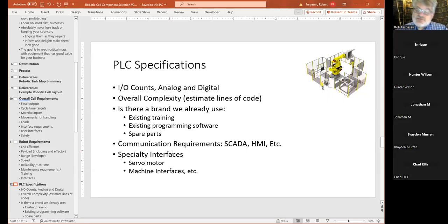And safety systems as well. Many of your more complex safety systems, if there's a series of conditions that lead to a particular safety requirement, a PLC is better at making those decisions. Most robots have excellent safety I/O, but if you have complex safety situations like this switch needs to be on, and this switch needs to be on, and this one needs to be off, and I can't have anybody within 20 feet, that's usually better off done in a PLC.